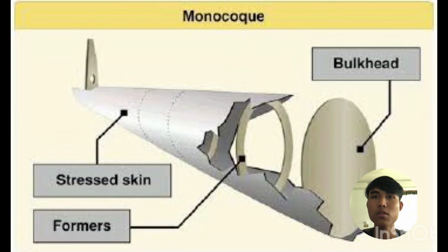Monocoque. Monocoque construction uses a strong skin to support almost all loads. Although very strong, monocoque construction is not highly tolerant to deformation of the surface. Because most twisting and bending stresses are carried by the external skin rather than by an open framework, the need for internal bracing was eliminated or reduced, saving weight and maximizing space.